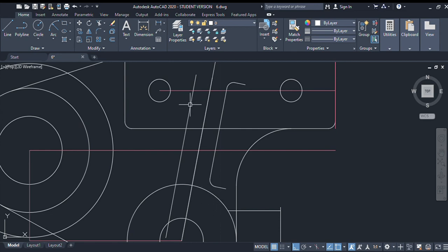in this line, I will create another line with a degree of 259 again. Length is 1.76. And then a line with an angle of 169 degrees. Then the length is 0.15. Then I will just offset this by 1.76. Enter.